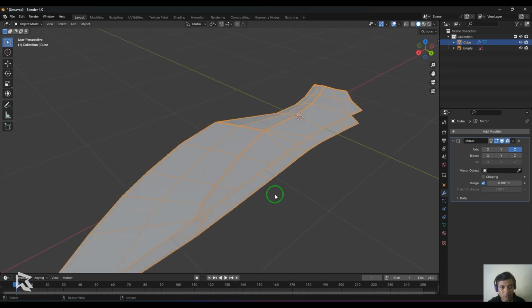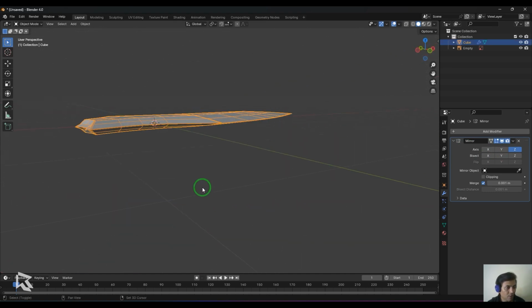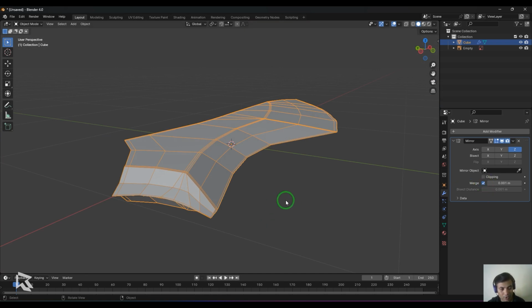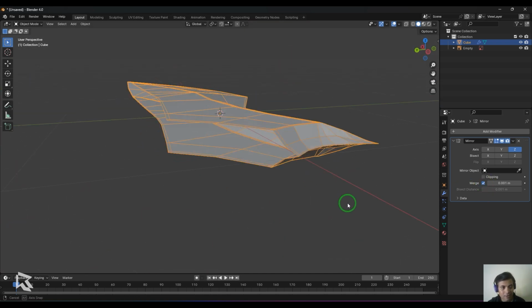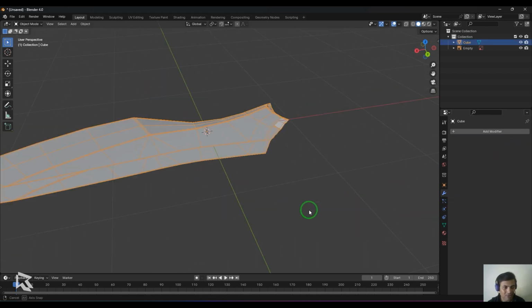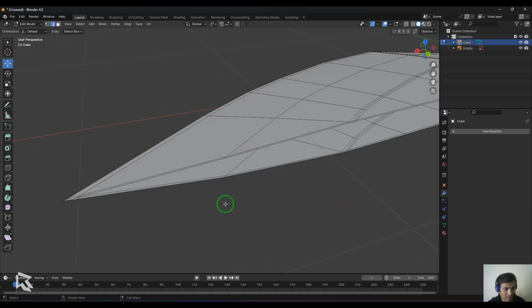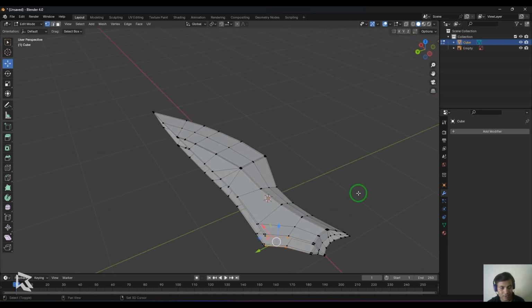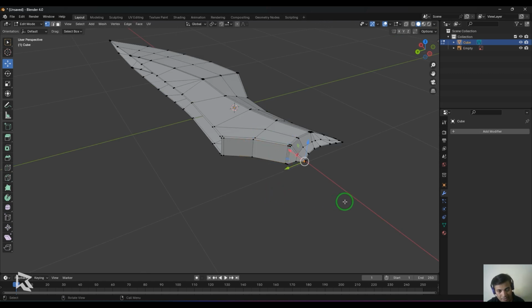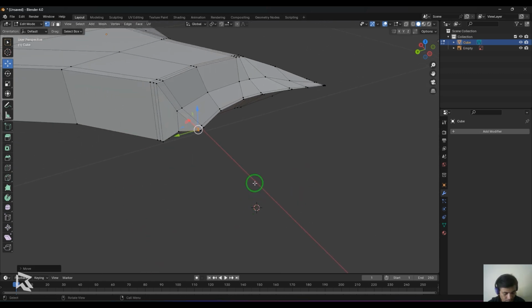Okay, so once that model has been mirrored, now you also have the option called merge, which is going to merge this border vertices. And just go to this particular option and then say apply. The mirror is gone and it became one piece now. Now I press tab and then press 1, and then you got the vertices, right? So what you need to do is select those 2 points on the upper side and 2 on the bottom side, press F. Then select these 2 points and then start pressing F, and then it starts filling those model. Okay.